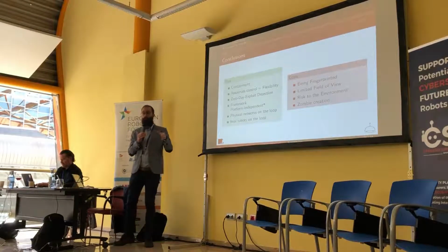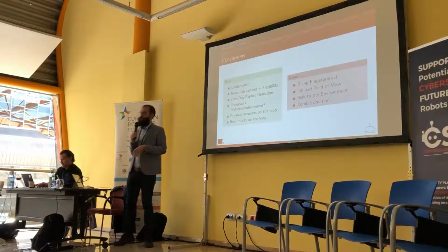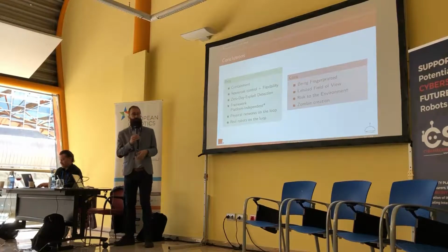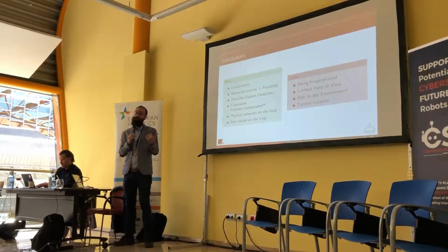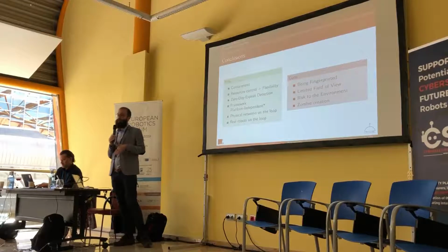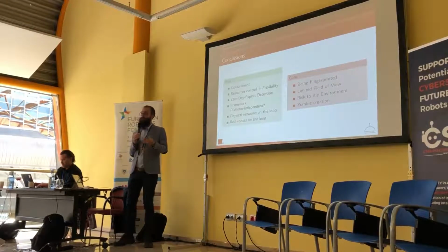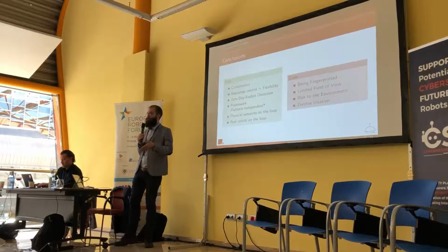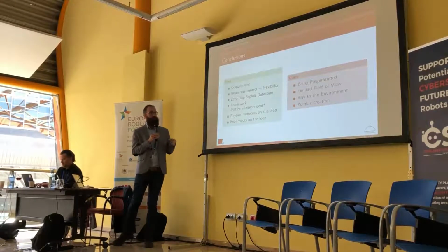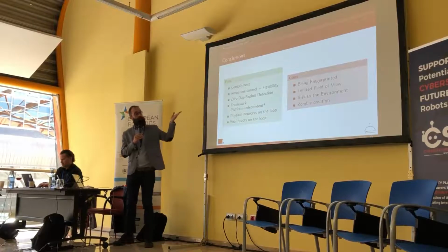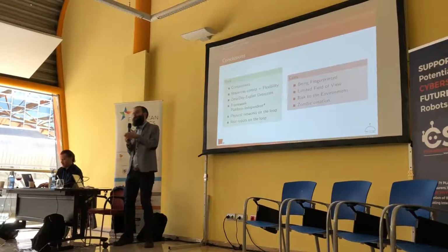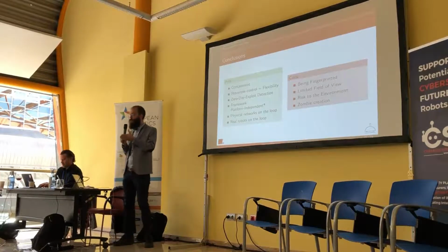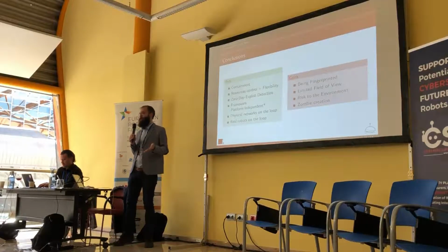That is in systems like ROS, Robot Operating System, one of the more static platforms. I think this concept is clear for everyone. In ROS 1, it was TCPROS and UDPROS, everything in plain text, a big hole there, and now we need to face DDS, which is the future of these communications. Of course, the con is that some of the roboticists interacting with us discover easily that they are in a honeypot, because some of the hardware components are not there, as they are limited. Okay?